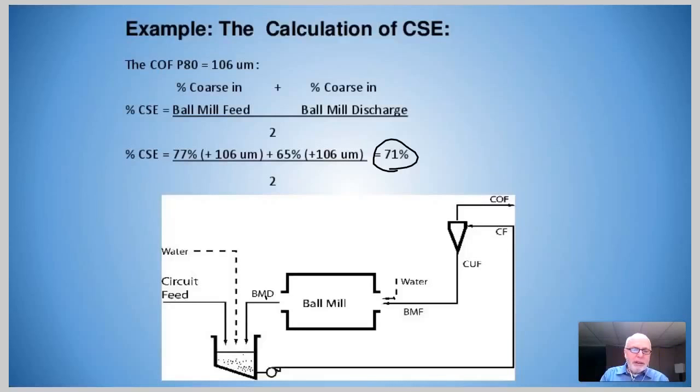But also the amount in the discharge depends on how long the material is in the mill. If the residence time is very long, we'll have a large buildup of fines, and the mill will contain a lot of product size material. If it's very short, that is a high throughput or high circulating load ratio, then we have a minimum buildup of fines.